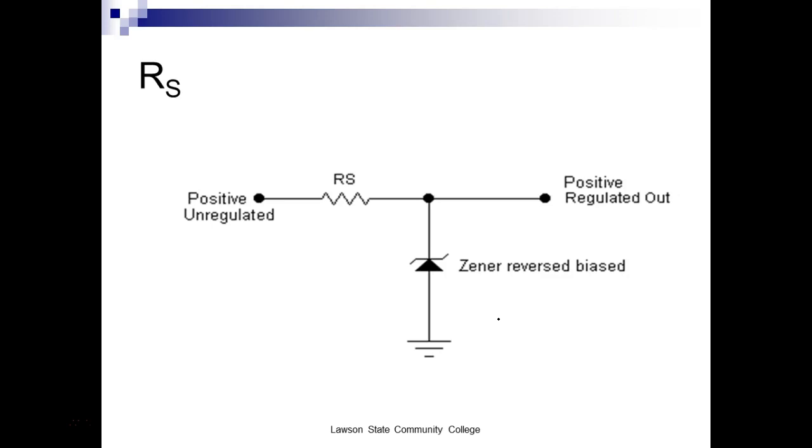Regulating the voltage. Not the current, it's the voltage. Later on, when we get into bipolar transistors, I can show you how we can make current regulators. Here, we're going to use it to regulate voltage. So we'll let the voltage change. And when we talk about a regulated power supply, what does it mean? Well, it means things can vary, but the output will stay the same. If it was perfect, but there's no such thing as a perfect regulator. Even regulated power supplies give you what they call a percent regulation.